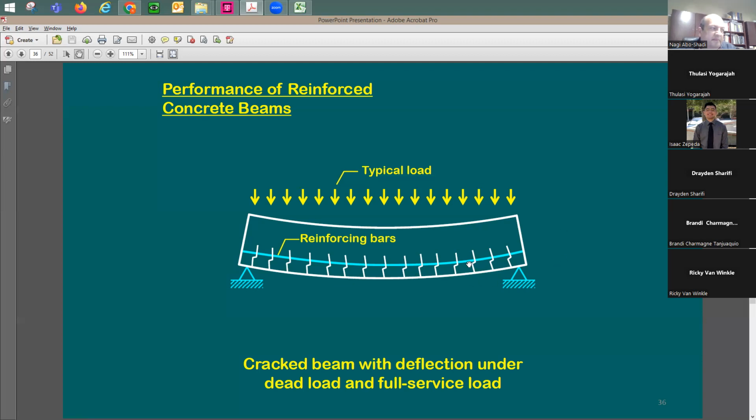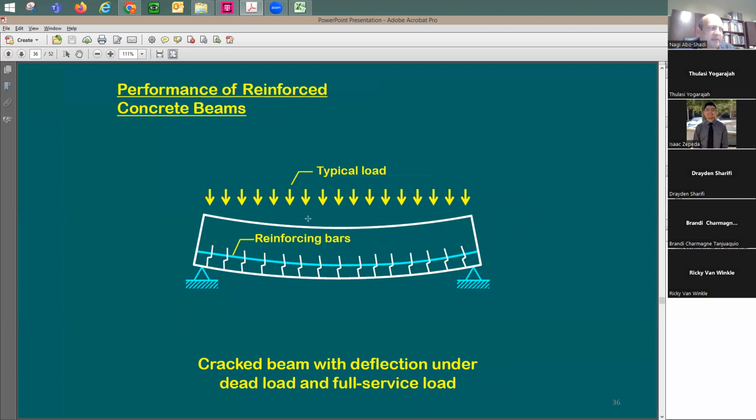After that, the beam rebars are going to start to take some tension force. It's going to continue, the crack is going to extend. The neutral axis is going to start to come from the middle. The mid height of the beam is going to be shifting up. Usually, the zone is going to be severely cracked right in the middle. This is where you have the maximum moment. Once you go right and left, the amount of moment is going to drop down, and the amount of cracks also is going to be reduced. Meaning, no load, no stress in the beam.